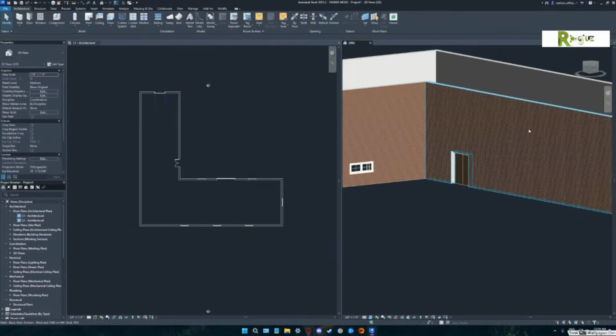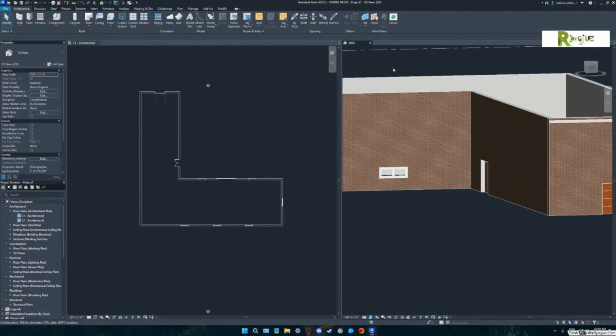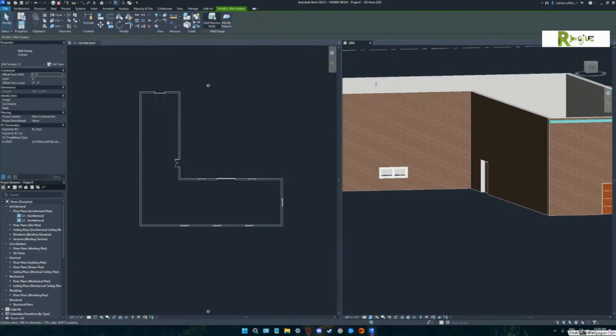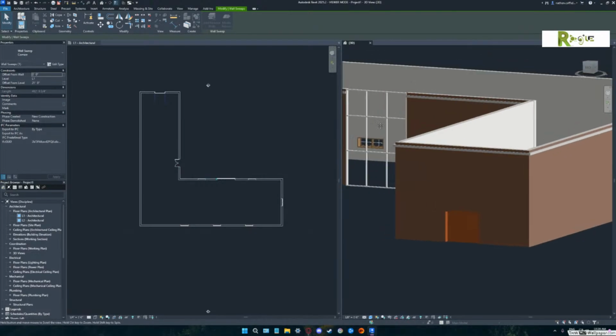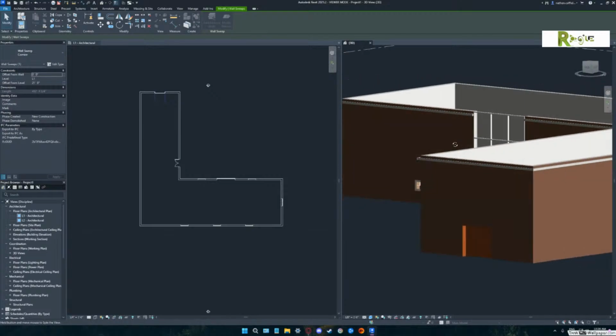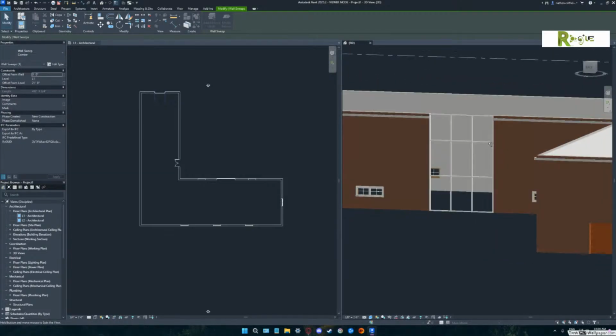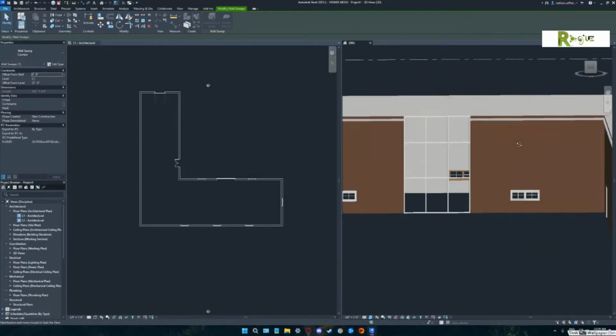Now do your orbit. Now there you go and pick. See, you're picking, you're off by one sequence. You should be able to add all those walls all the way around. Go ahead and pick that next wall. Okay. See, that's what you weren't doing before. Now, you can do that same thing to add a reveal. So you can add these sweeps and these reveals.